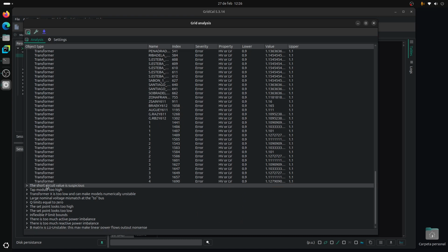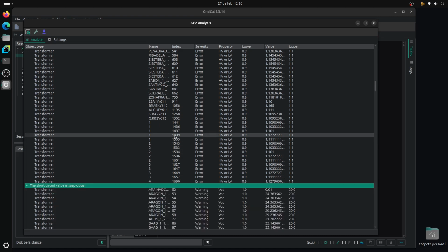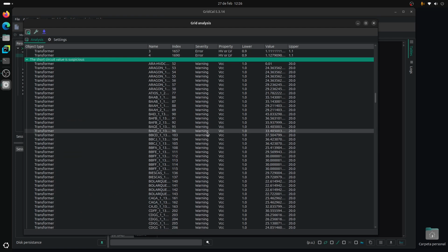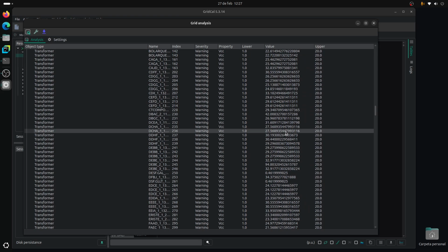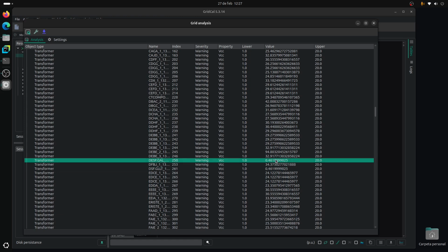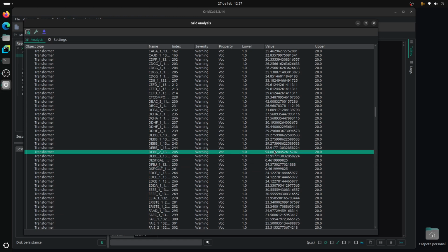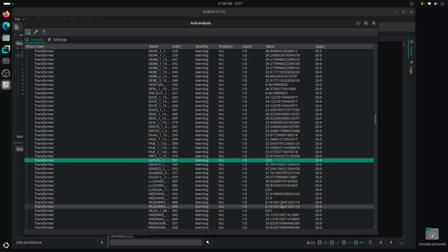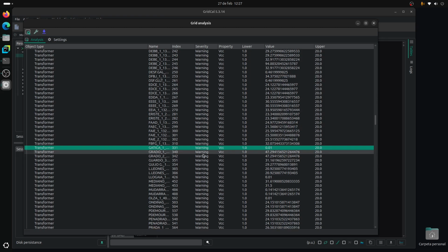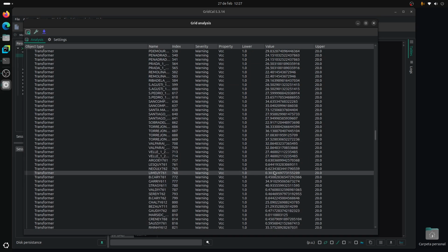The short circuit value is suspicious. Usually, transformers have a short circuit value of around 20%. So this, well, could be, 20 something. Yeah. This certainly, suspicious. This 94%, definitely not possible unless you made your transformer out of plastic or wood. This doesn't exist either. So all of these are data smells, stuff that probably tells you that this is modeled with incorrect information.